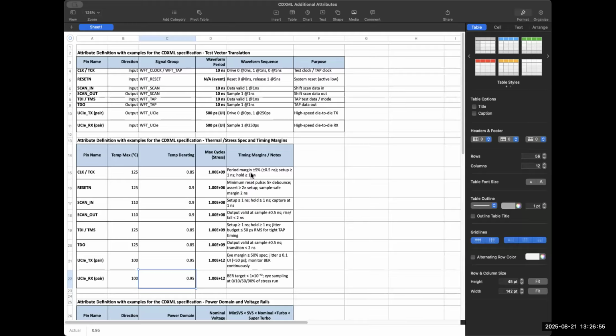These pins need to be remapped. In general they're all internal pins, and some, possibly all but most likely not, are going to go externally. Some of them may get daisy chained to other chiplets.